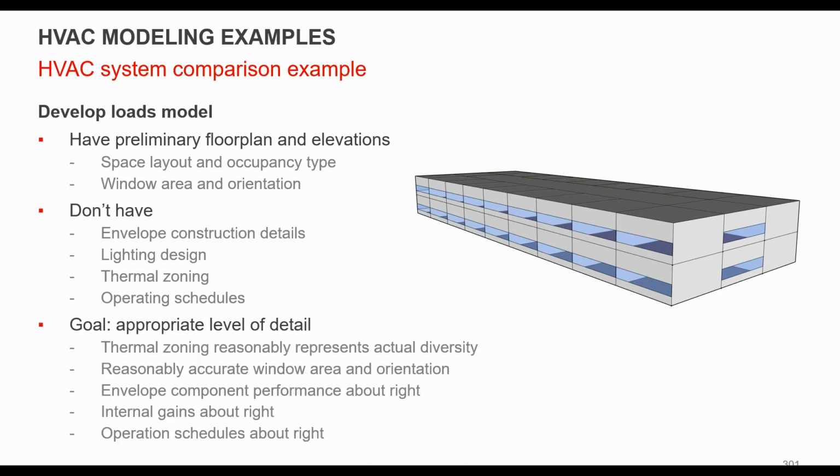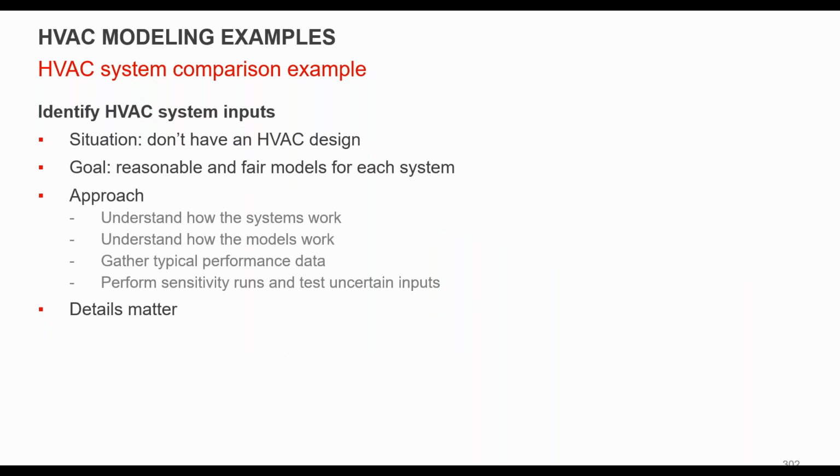And then finally, what do you want to do? You want to get the right level of detail. So important things here, windows, as I mentioned, you want to make sure internal gains are reasonable for this type of building and your schedules are reasonable. And for most of these things, you can get pretty good data. But again, the idea is document it, make sure that it's easy to follow up and easy to review.